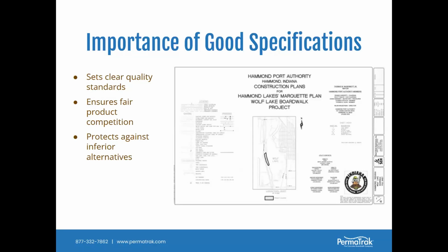Number one, a good set of specifications is going to provide a clear outline of what you and the designer are trying to accomplish, properly detailing where the boardwalk is, what the boardwalk consists of, what the alignment is, what the foundation system is, the foundation depth, providing all of those so a contractor can clearly give you what you're expecting from this project.